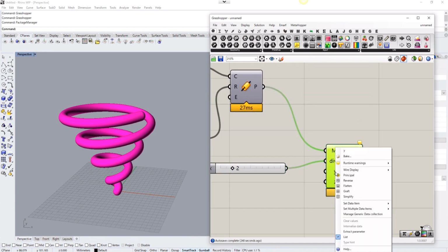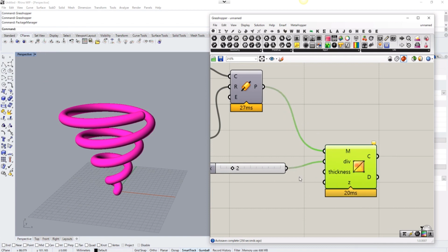Now for the second parameter I'm adding, it's going to be thickness, the thickness for the outline, since we're going to use an outline. The Toon shader would like to create a black outline on the outline of the meshes, based on the normal direction of the meshes compared with the camera direction.